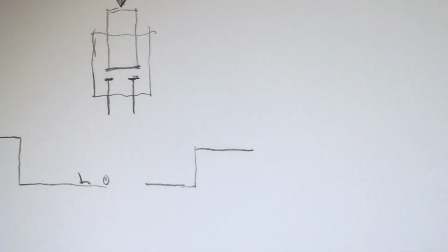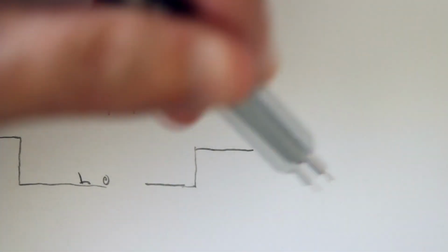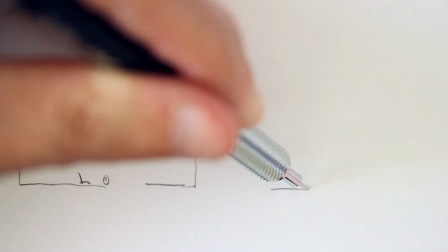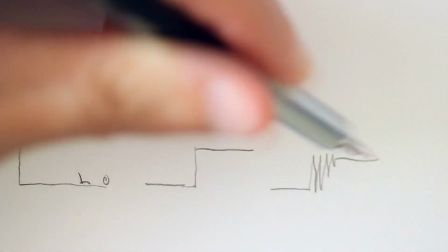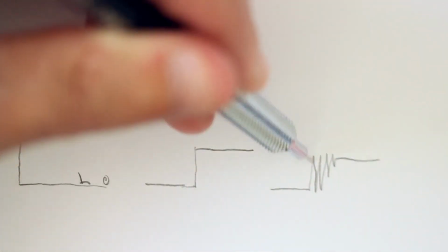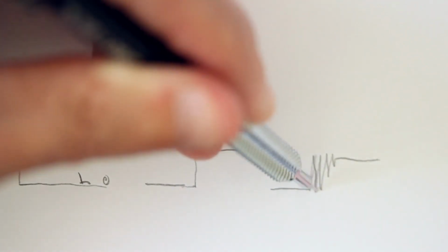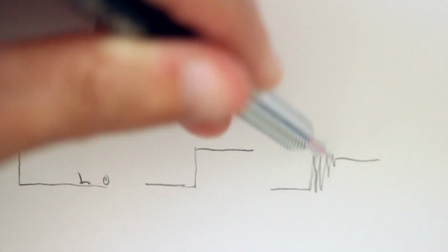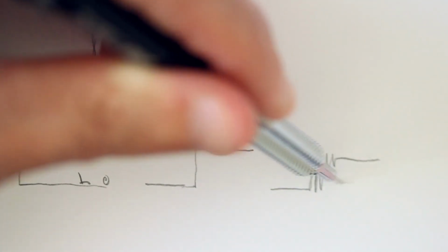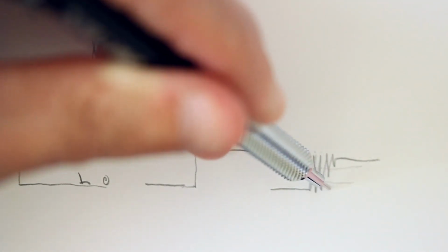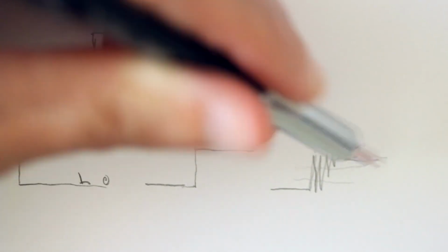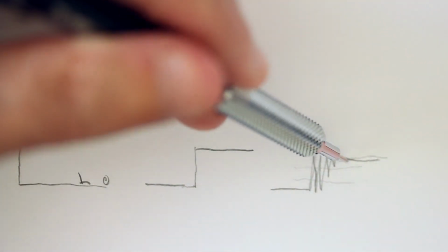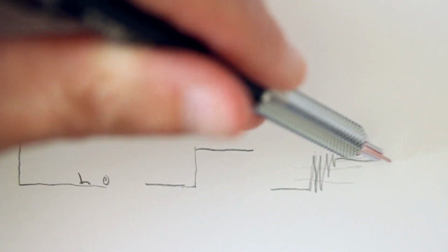What is actually happening, however, when you're pressing a push button is it's starting low, and then when you press it, it could be doing some jumps before it gets to the high digital level. In software, you're going to be able to see all of this. You're going to see it go from 0 to 1 to 0 to 1 to 0 to 1. If it goes below the thresholds, you may see it go back to 0 or not. Then, if it's depressed for a period of time, you should see a good signal of high. We would like to eliminate this portion.